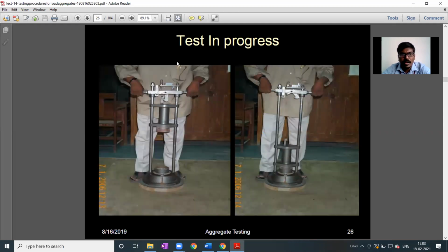If you have not seen it, here you can see the hammer is locked here. Whenever you touch this top surface, the straight part becomes inclined this way, so the hammer lock is removed and it falls on the aggregates. Within the cylindrical measure you can see the test cup and the aggregates. The hammer, about 14.5 to 15 kg, falls on these aggregates. In that way we give the impact load or sudden load to the aggregates.